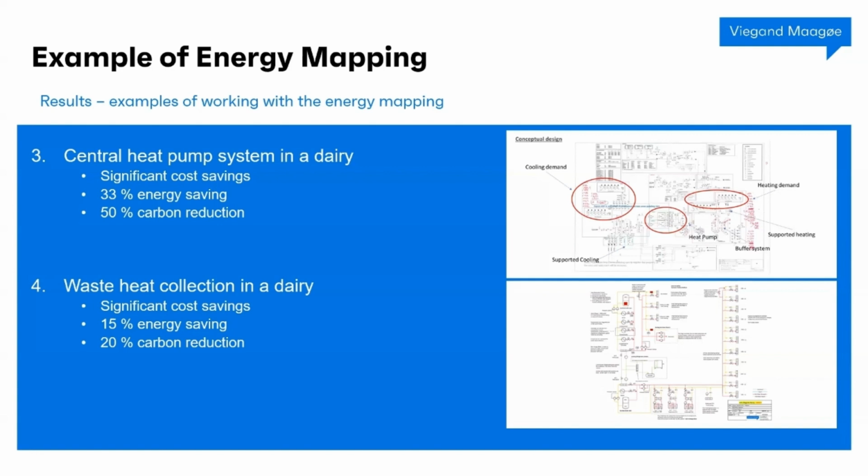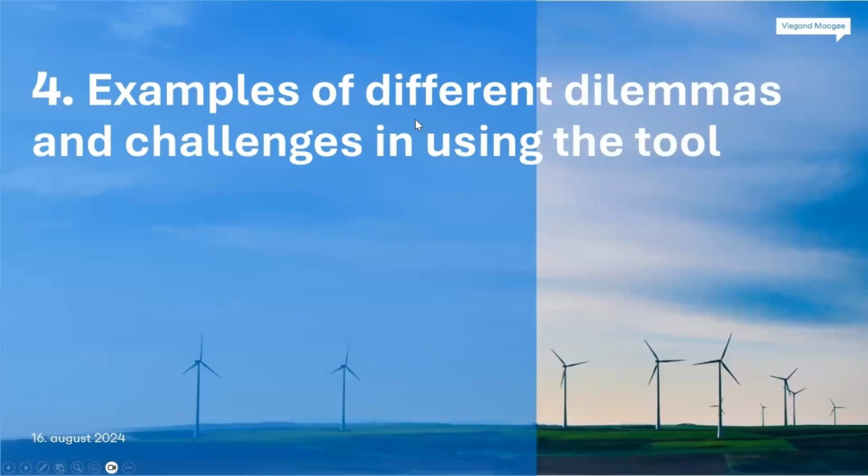We have some heat recovery potential from the air compressors, from the cooling systems, also from some flue gases. And we merged that into a recovery system, and we could cover a lot again of the low temperature heat demand. So putting this into, in this case, an existing low temperature system, just leaving out the fossil demand.